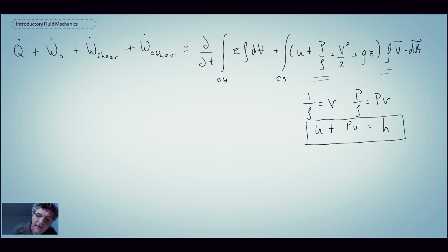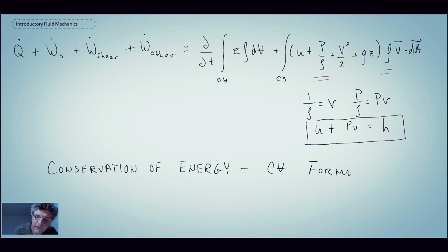So that is essentially the enthalpy term, and that's the term that's associated with the flow work that you would see in a thermodynamics course, which is consistent, and it should be, because the conservation of energy in fluid mechanics should not be different from the conservation of energy in thermodynamics. And so what this is, is conservation of energy, and it is in the control volume formulation. So it enables us to apply it to situations where we have fluid crossing the control boundary.